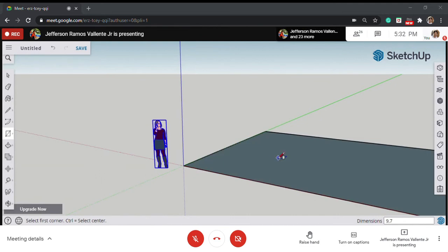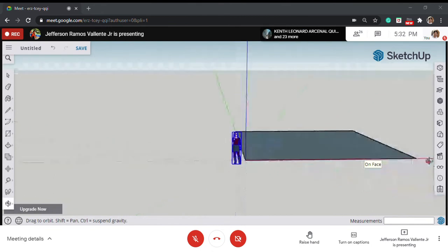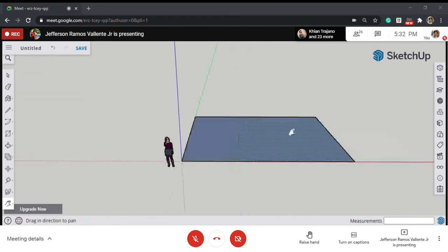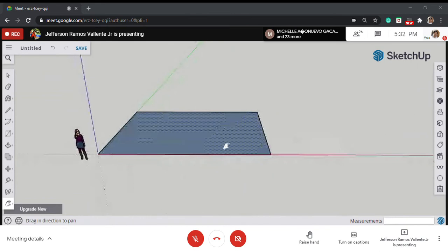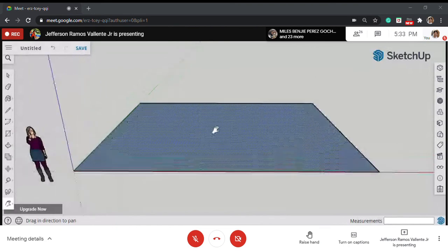Next, you will notice the rectangular shape. And make use of the zoom tool with your mouse and the pan tool by pressing the scroll longer and then moving it a little towards your object. So that you can orbit it. And to move them, you can use the H command. In AutoCAD I was used to a different command. H is the hand tool where you can move your object, or your view. So I move from left to right here. And then zoom using your mouse, just to position it properly.